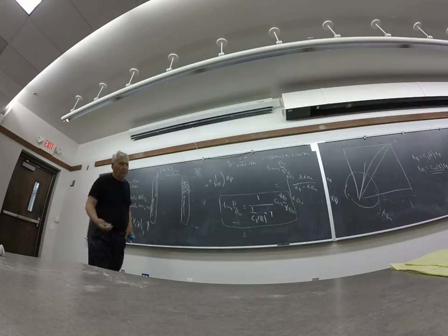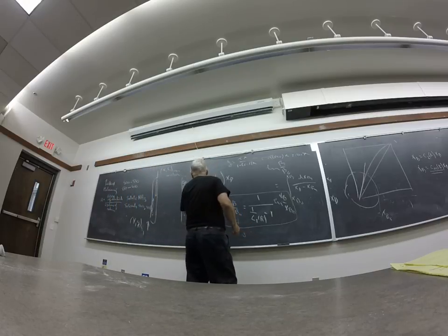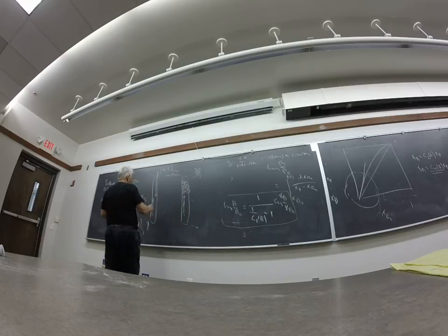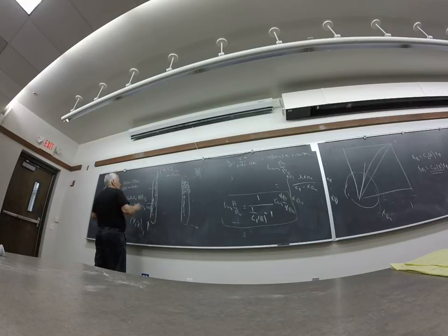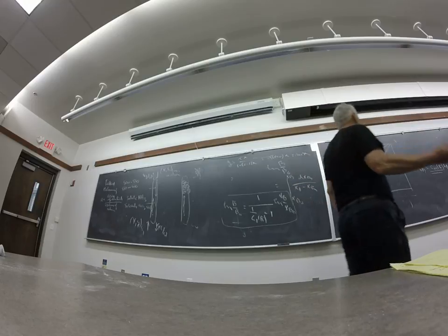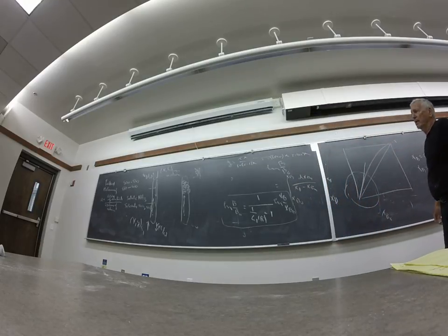Okay, now, what is our job? Our job is to decide how fast ammonia is leaving this phase and entering this phase. So the air and ammonia are flowing up here. The ammonia is leaving the air, coming in here. Finally, you take a V and a Y out up here, and you take an X and an L out down here. And you might want to predict what these compositions are. You might want to predict how high the column ought to be to make a certain separation and so on.